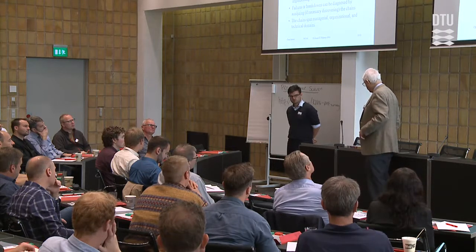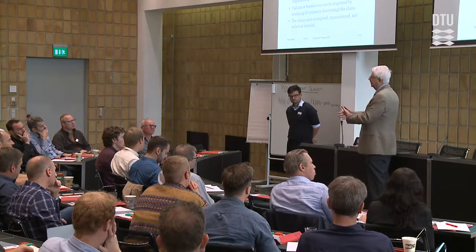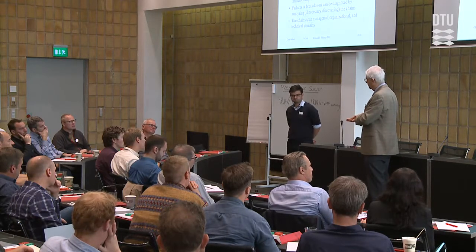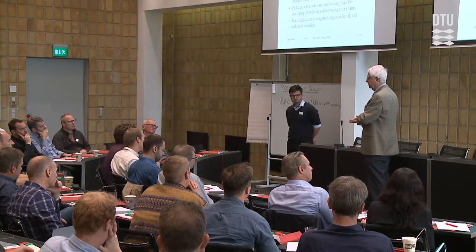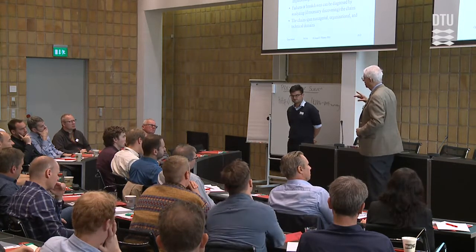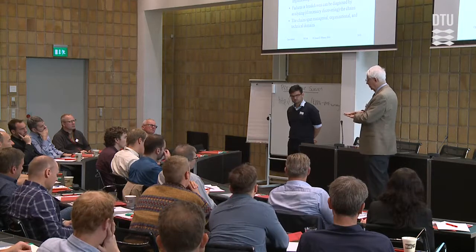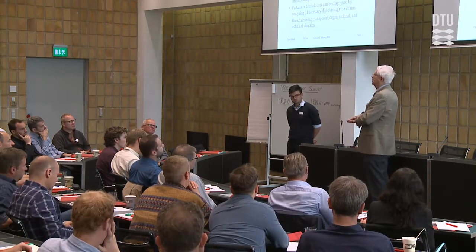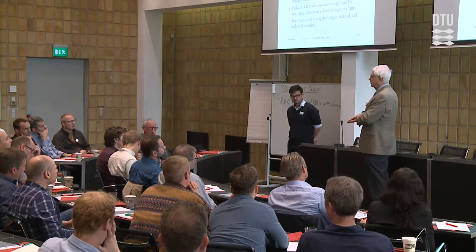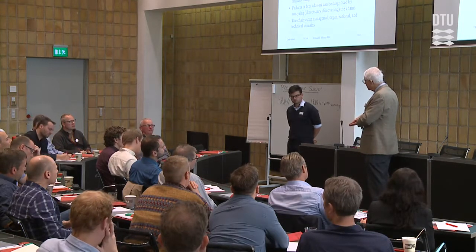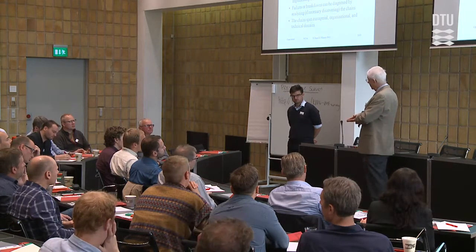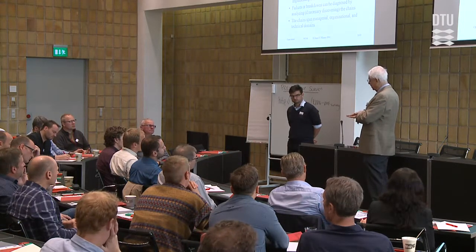It's unavoidable, as I said before, that these chains are going to share parts, that more than one chain is going to pass through some of the parts. And those parts become very critical. And we call this coupling. Coupling can be benign in the sense that you have enough degrees of freedom to adjust independently. Otherwise, it's called conflict, in which you don't have enough degrees of freedom to adjust independently.